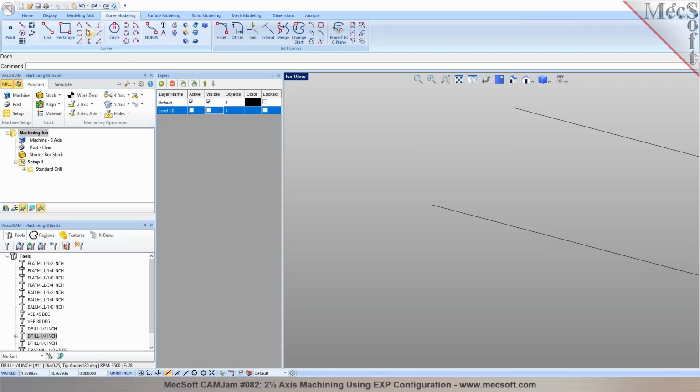I can go to the arc commands in here. You can see there are different ways we can create an arc. You can use the three-point arc, or you can do start and end, or I can leave one of these arc segments in here and create an arc and use the snap tools to snap to the center, and I can get the center point. As you can see, the center of the arc is right there, and then I can use the endpoint snaps to snap to the end of the line, and I can recreate those arcs right there for us, right? So I can recreate those arcs and use them as my control geometry for programming it.